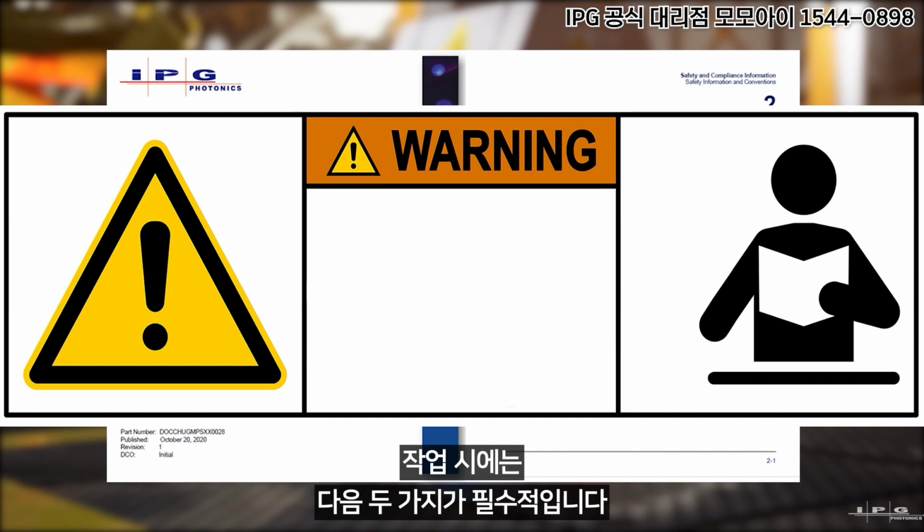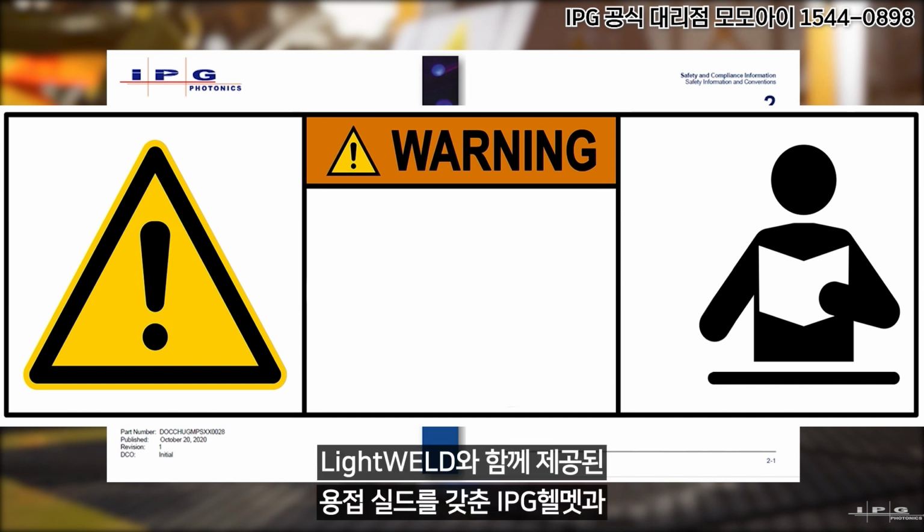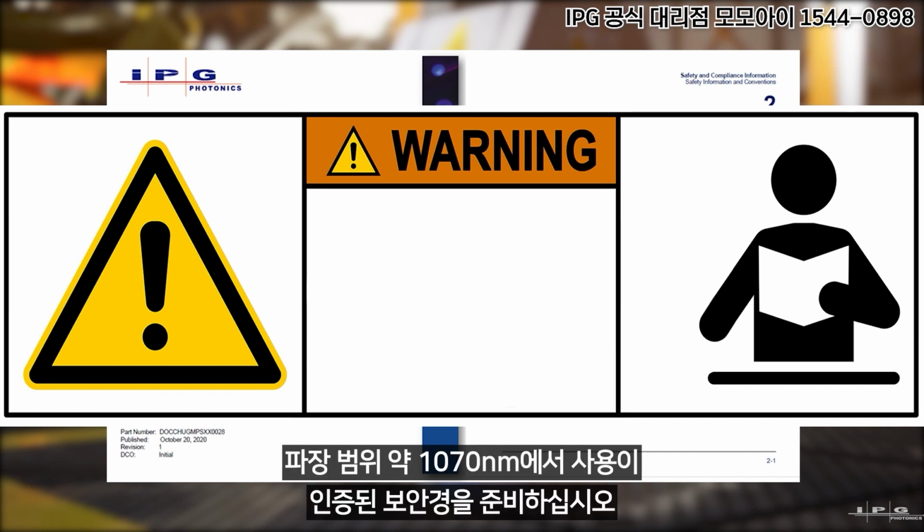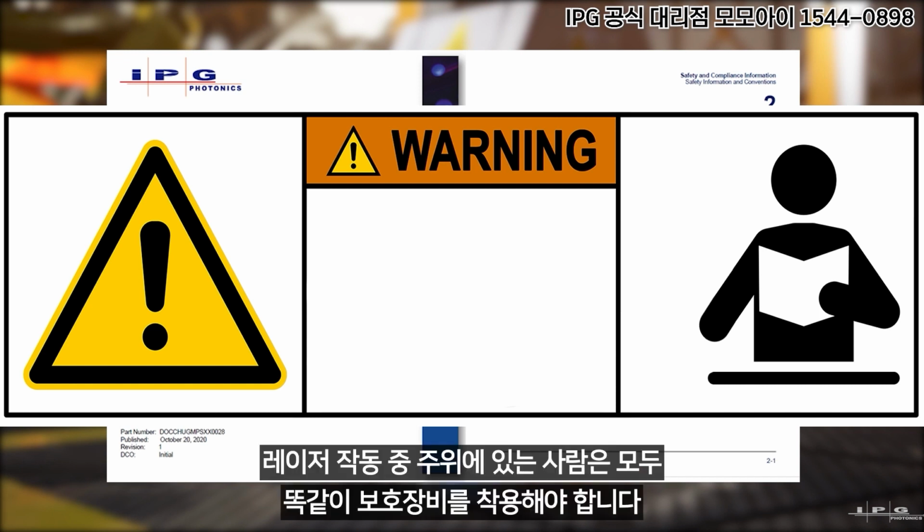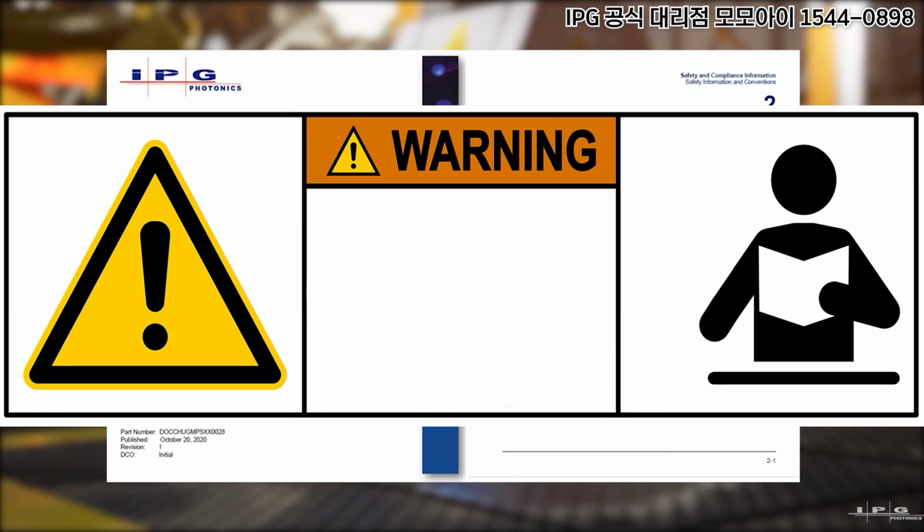Do not operate without both the IPG welding helmet, with shield provided with LightWELD, and proper safety glasses, certified for approximately 1070 nanometers. Make sure everyone present during laser operation is also equally protected.